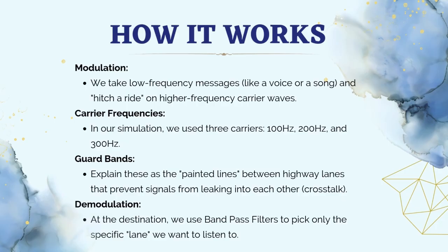Finally, at the destination, we perform demodulation. We use something called a bandpass filter. You can think of this as a specialized exit ramp that only allows one specific range of frequency through, while blocking all the others, so you hear only the message you intended.